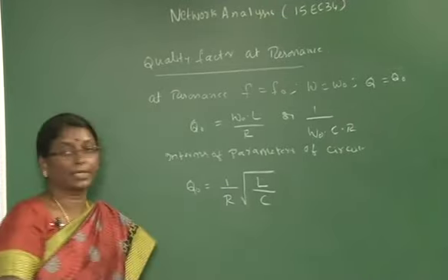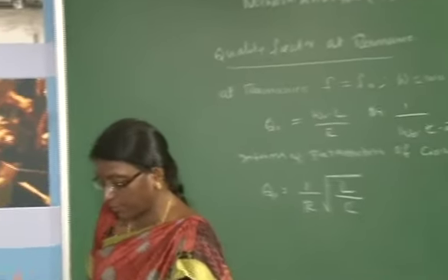These are the quality factor of a circuit which is given. Till now we have discussed only what the quality factor is. So what is the significance of this quality factor? In the resonance, if you check the resonance curve, as the frequency is varied, current is varying from minimum to maximum at resonance, and once again as the frequency increases, the current is decreasing.